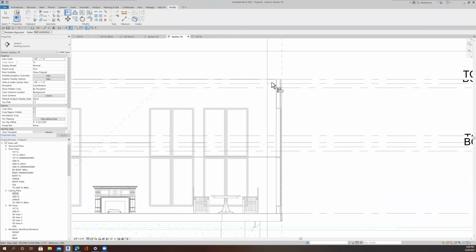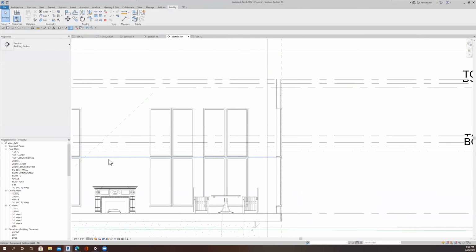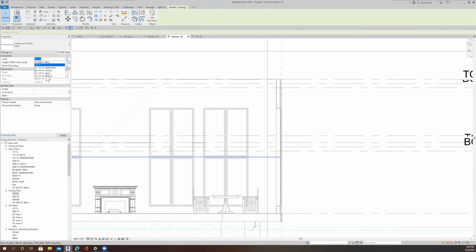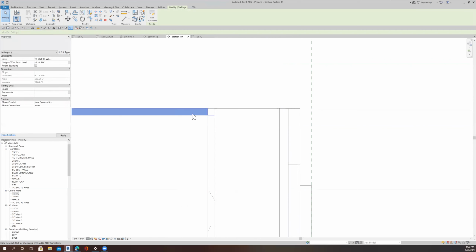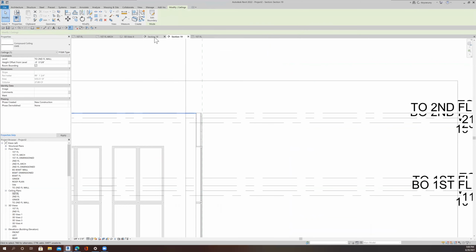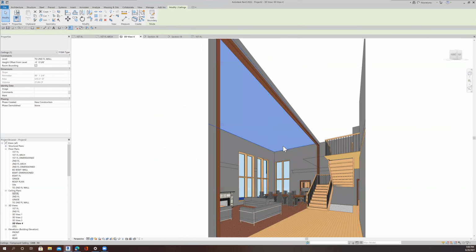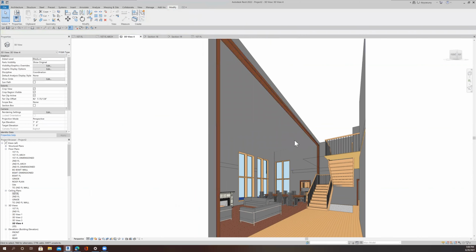All right. Then let's do it this way. Let's change the properties. The top of second floor wall. And now let's put 0 offset to see what happens when we do that. It's 5/8 of an inch too tall. So now we'll just subtract minus 5/8 of an inch. And my gypsum board is exactly where I want it to be. Let's go back and take a look at my ceiling. Now I have a ceiling up there.